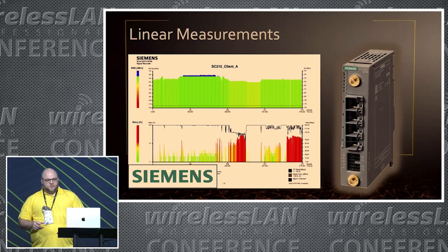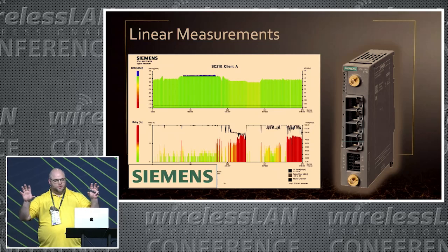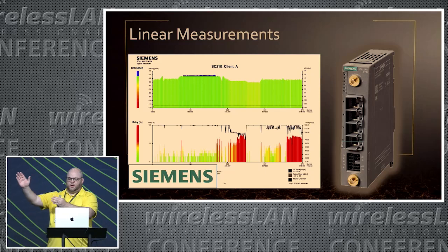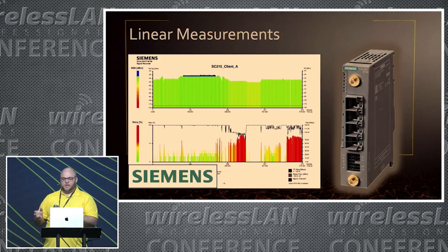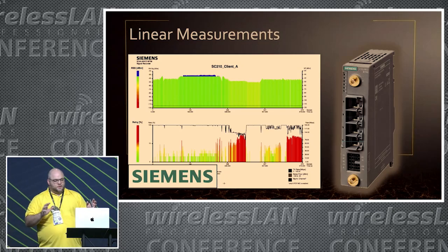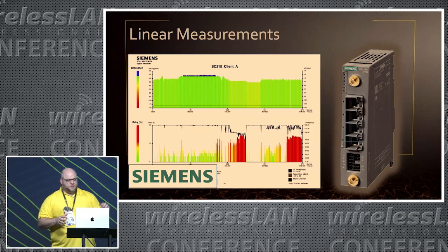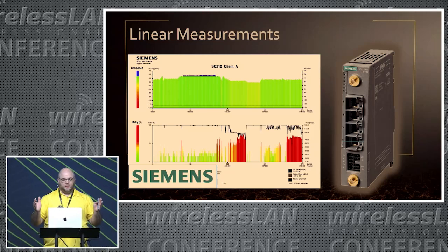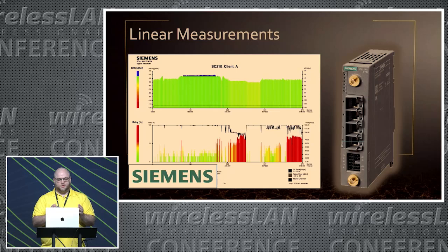In this example, this is a stacker crane, so it basically stores rolls of steel in a big long aisleway, big tall crane. And this is actually one link of a PRP link, so we had dual wireless links to this. I thought this was a good example because you can see there's a little blue line at the top, so it's highly directional antennas. When it gets really close, we're going several hundred feet. We're over-modulating the radio, so we see incredibly high signal.